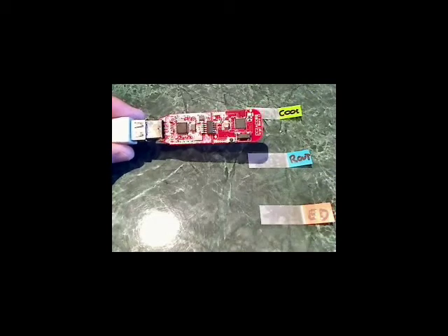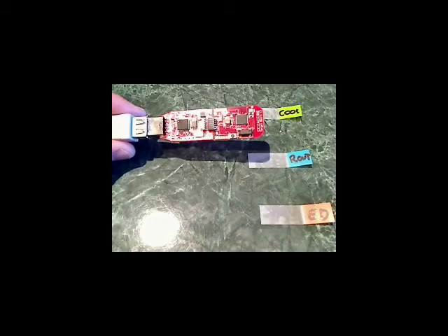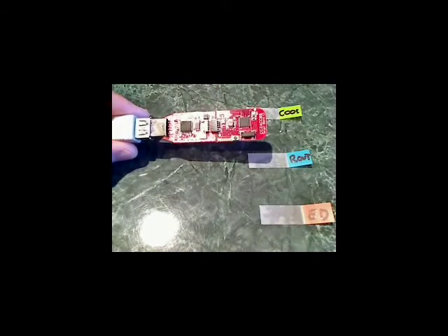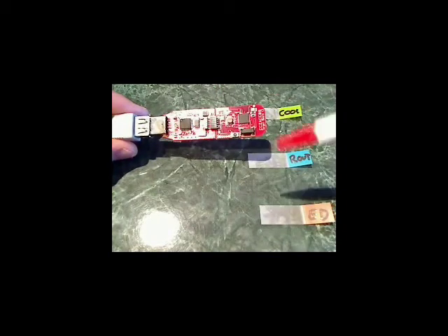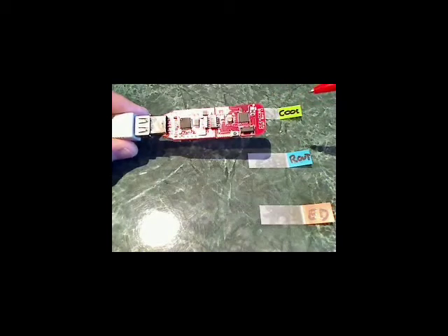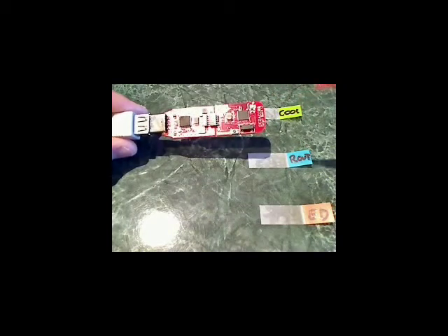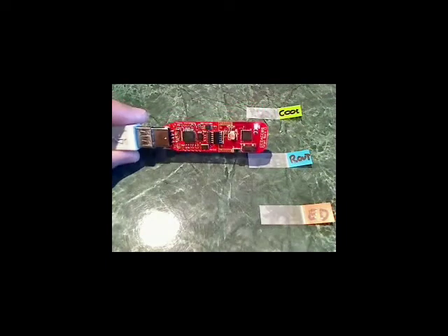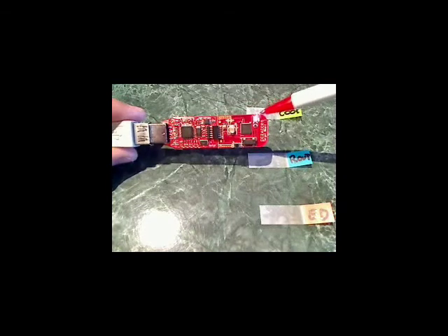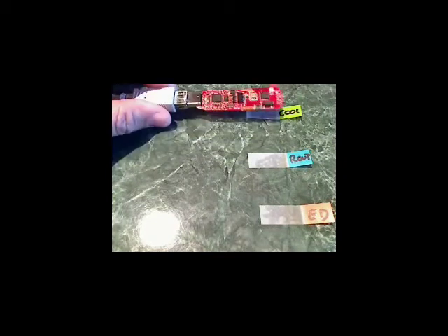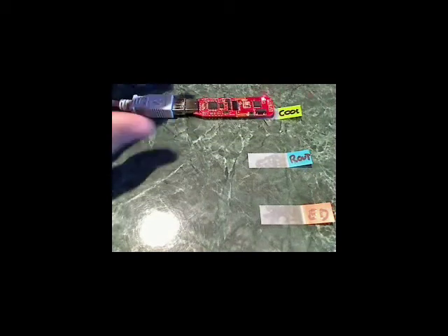All three boards are running exactly the same software. Their functionality is only changed by the pressing of the switch. Now, I'm going to press this button right here once, and the board is going to go through a sensing to see if there are any other networks out there, and it's going to act as a coordinator. And in just a moment, the red light comes on. Hopefully you can see it. This red LED is on, indicating it's the coordinator. So I'm going to place that right there where it says coordinator.